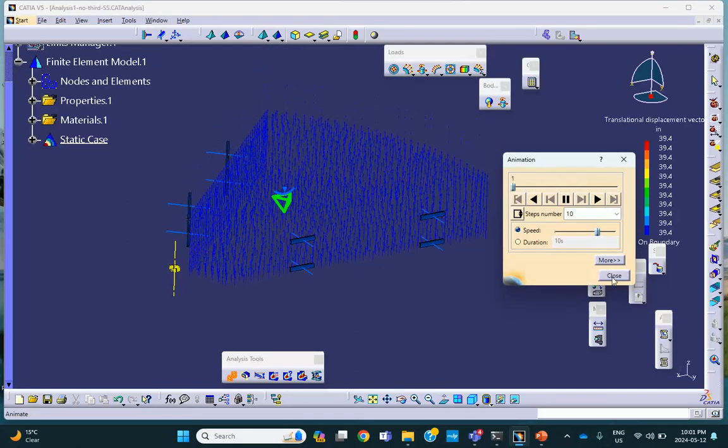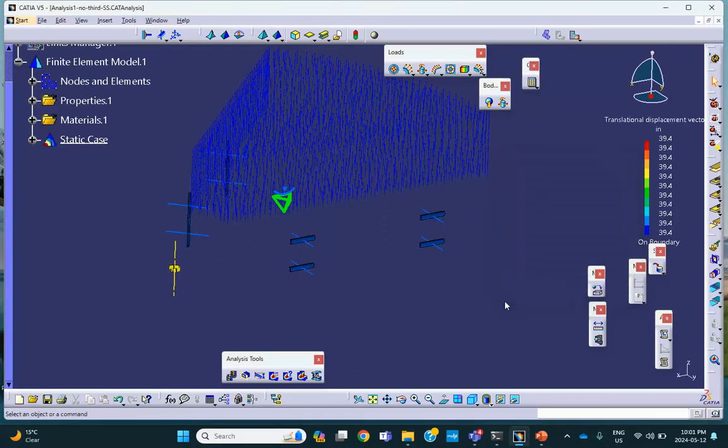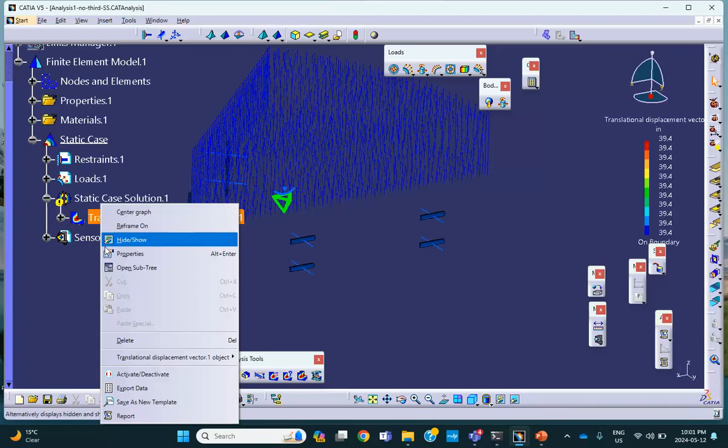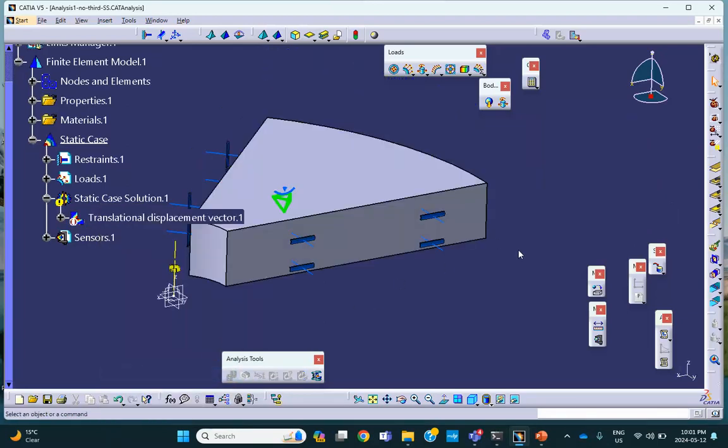Okay. We say okay, and we deactivate the spot because we want to fix the problem. To take the rigid body motion away, I take one point and say, hey, you cannot go up and down. It doesn't matter which one of these points I take. So I'm going to go to user defined. See that? Remember this?